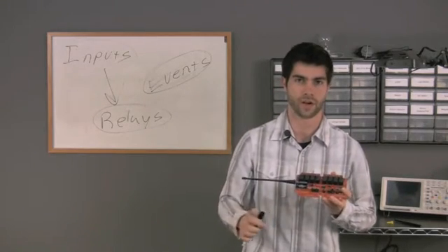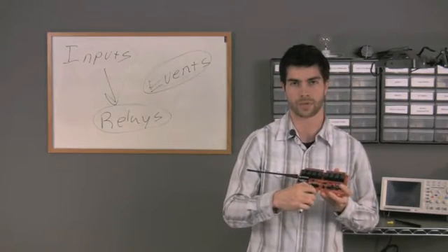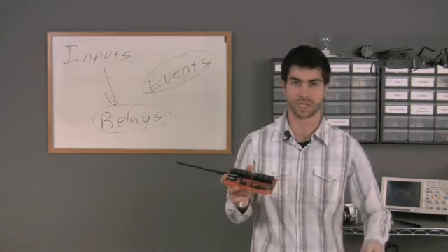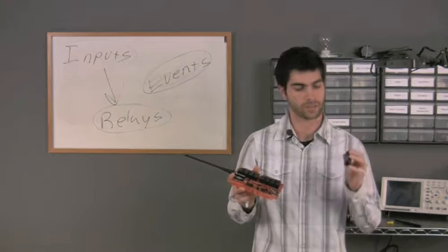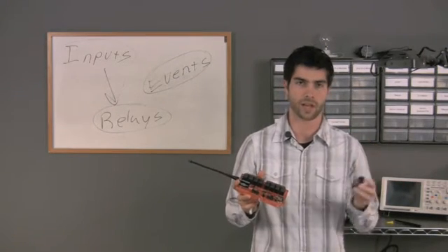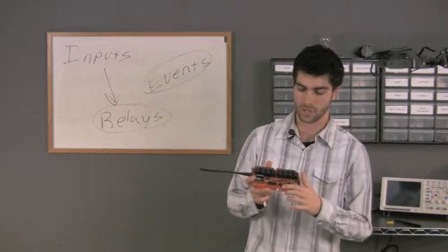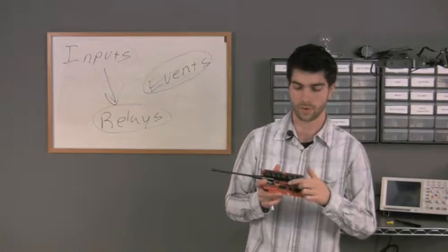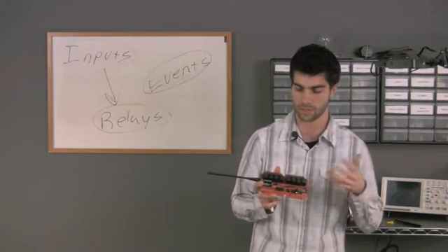You'll notice on your key fob controller you don't have 8 inputs here. That's because 5 of the inputs have been dedicated to your key fob. Now, if you happen to have more than 5 buttons on your key fob, if you have an 8-button key fob, you can actually change these little jumpers here so that you can dedicate these inputs to the key fob or to these A to D inputs, so you have the option.